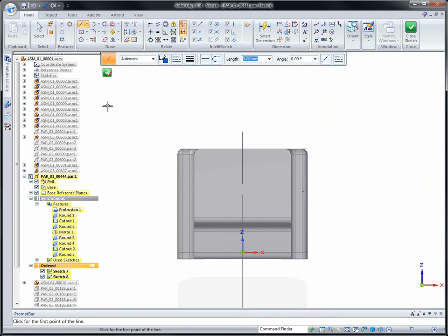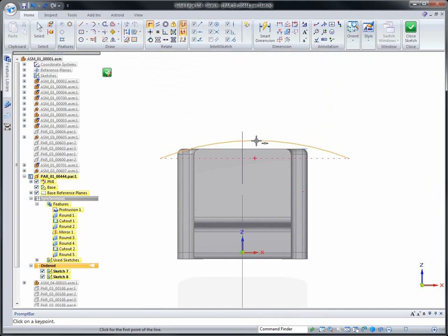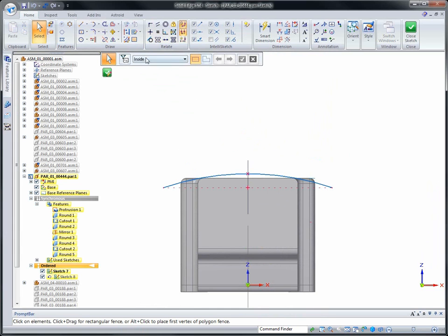Using Solid Edge's sketching tools, we'll just create a 3-point arc, and we'll use the alignment indicators to make sure that the two ends of the arc are aligned with each other. You can also connect the midpoint of that arc to the center line of the engine cover. Next, we're going to convert this from an arc to an actual B-spline curve just with a single mouse click.